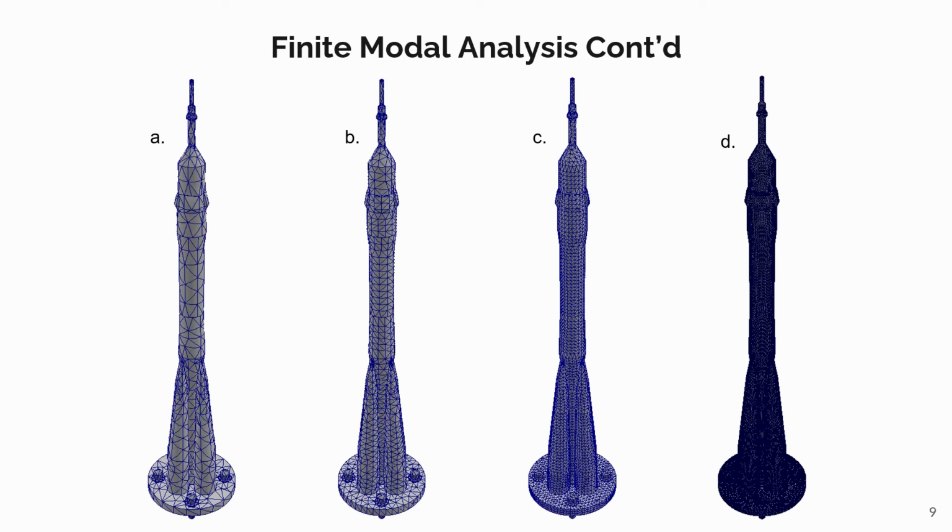Finally, we performed a mesh refinement study to ensure that the results of the simulation were not dependent on mesh size. We tested multiple incremental refinements between these 4 images and ultimately settled on mesh C.